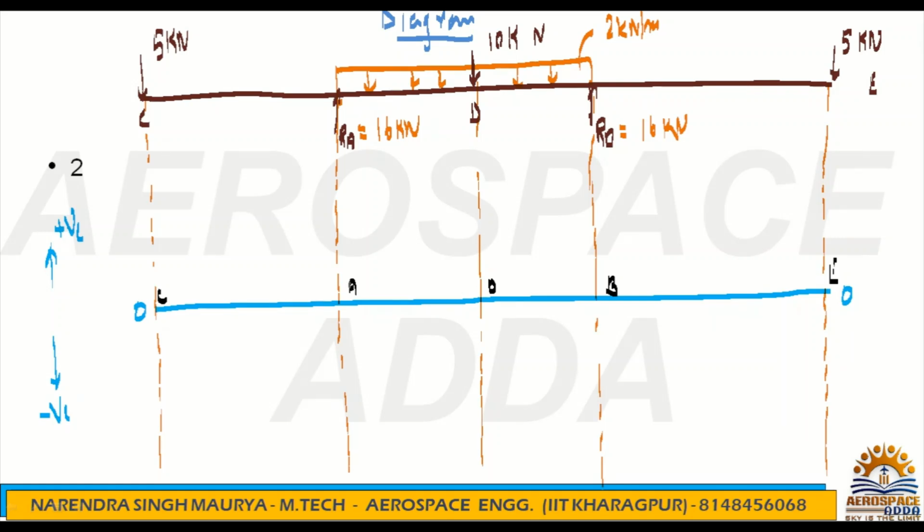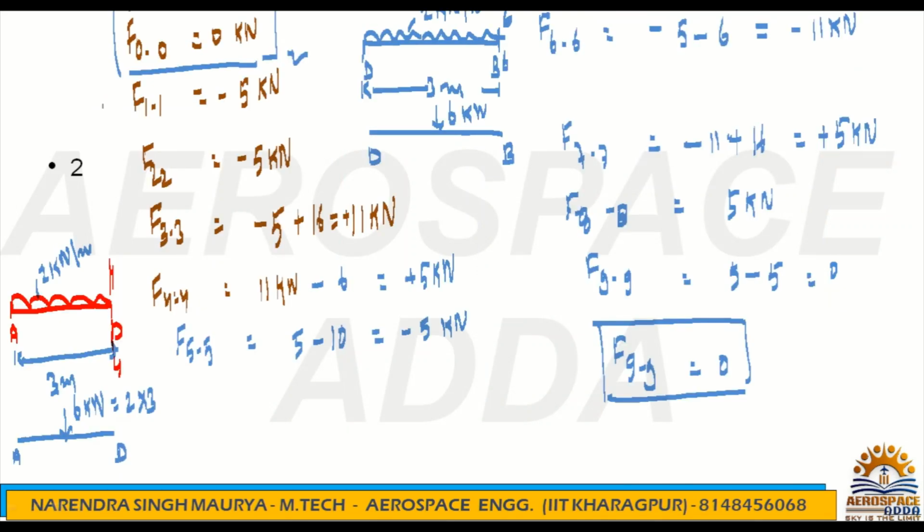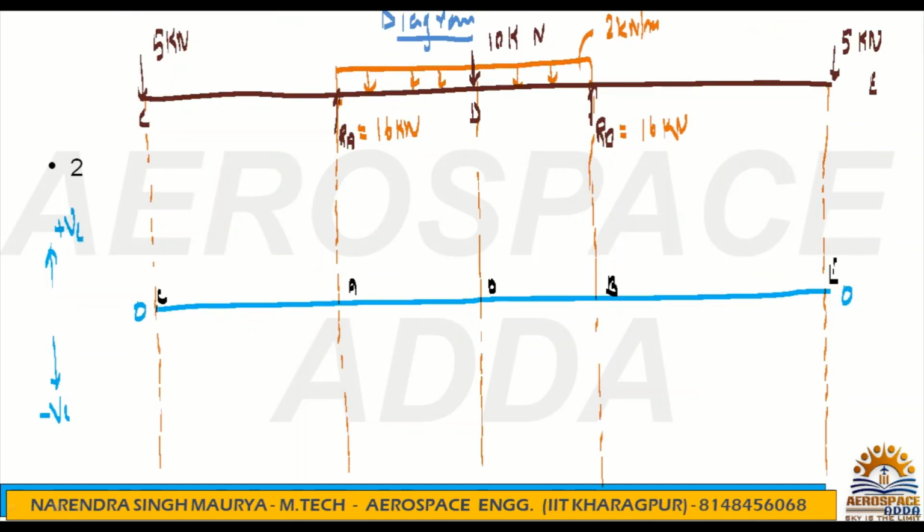0-0 means it's a number, it's not a symbol. It's a reference only, above positive, below negative. Okay, so at C, if you check the shear force, here we have to go. See, section 1-1, just after the up 5 kilonewton, what are you getting? Negative 5 kilonewton. Negative 5 kilonewton means you have to go down. This value is nothing but 5 kilonewton. If you are going down, don't write the negative sign, it's automatically understood that going down means negative.